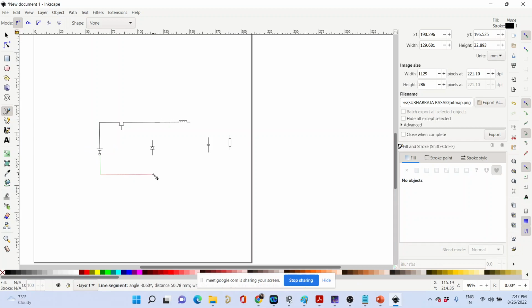Actually, I found the phase voltage, that is VA equal to VL by root 3. I got 100 volt at zero reference. That is VA equal to 100 at angle 0 degrees. Next, VB equal to 100 at angle minus 150 degrees. VC equal to 100 at angle minus 240 degrees.